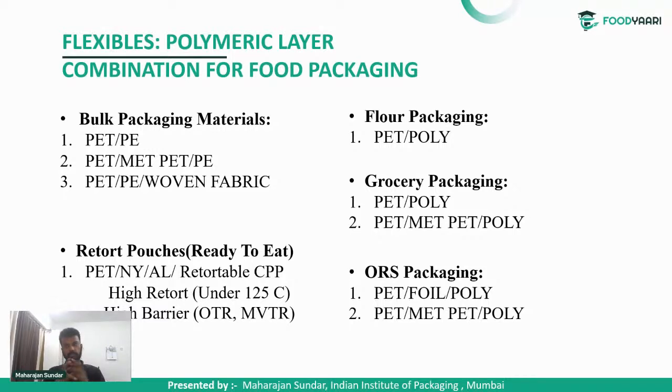Wear resistance, in the sense that we can use it for high temperature applications, and for opening and closing of things. Retortable CPP will be the outer layer, and aluminum foil acts as the barrier layer. The nylon layer reduces the abrasion of the aluminum foil with the PET, which is the sealing layer. Nylon acts as an adhesive and abrasion resistance.